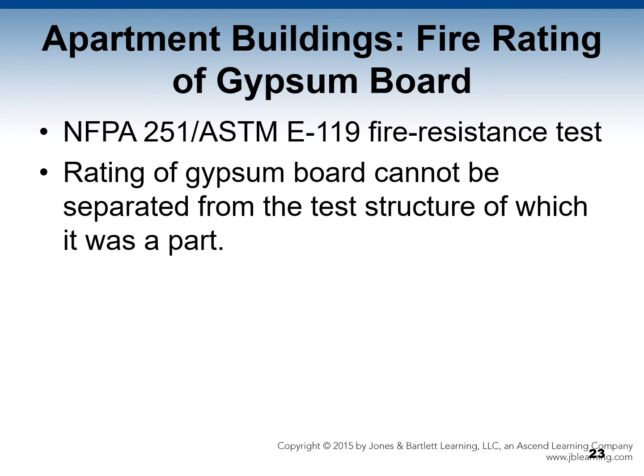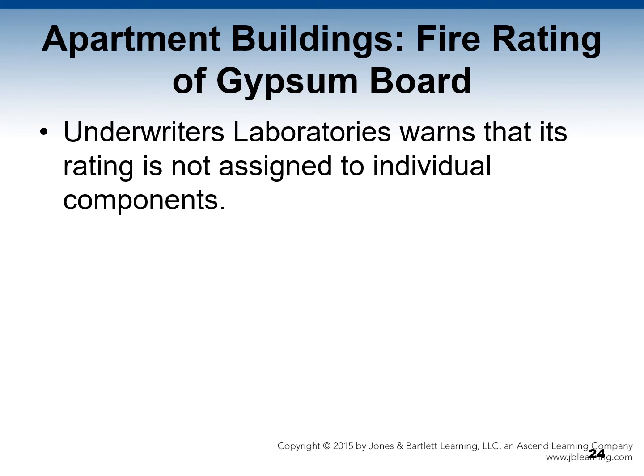itself. And bear in mind, while it is a fantastic material, it's used to separate units to prevent fire spread. Eventually, everything will burn given the right circumstances and temperature. Underwriters Laboratory, or UL, warns that gypsum board rating is not assigned to individual components. So it's testing a structure protected by a gypsum board enclosure as a whole, not the individual components. In other words, there might be one or two flawed components in that overall structure.